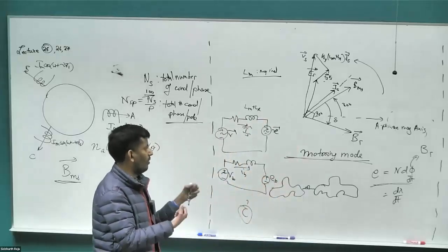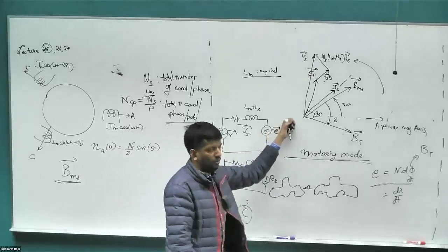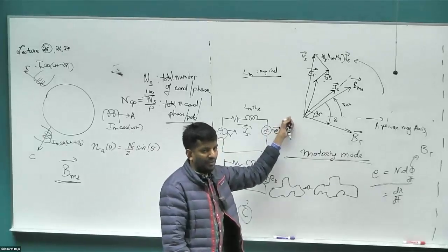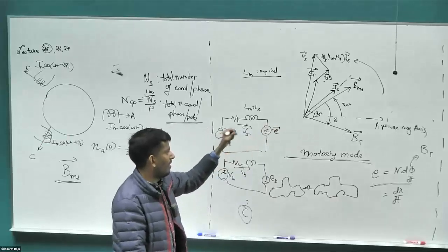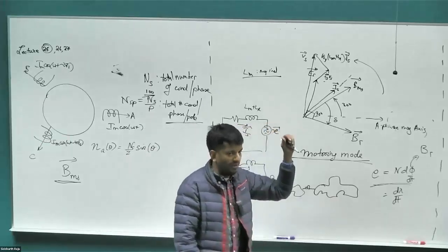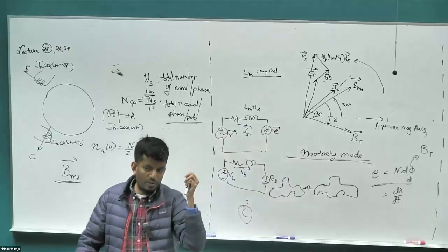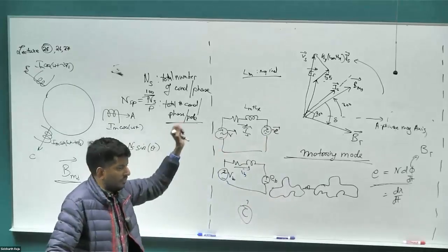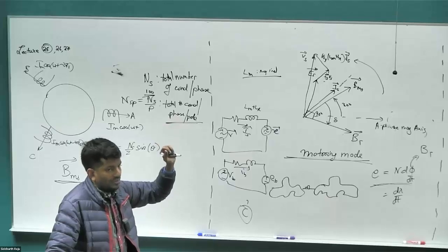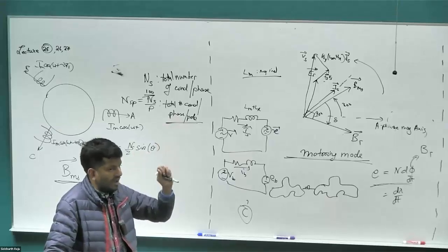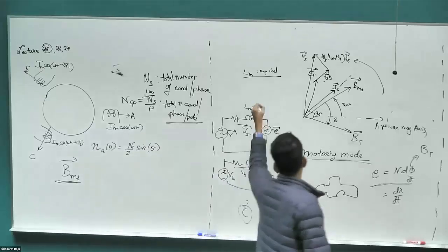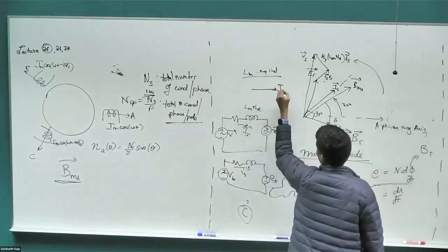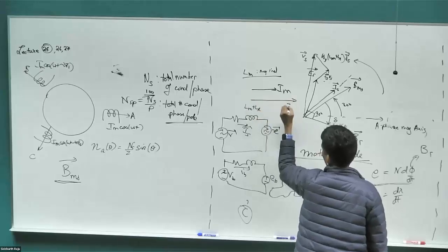All right. When you go to phasor, it's basically taking a screenshot of this space vector and drawing it for one particular time. That will give us the phasor value. In addition, you scale the value by a factor of 2 by 3. Because if the magnitude of your current is some 10 ampere, your space vector magnitude will be 3 by 2 times 10 ampere. But when you draw it as phasors, you will draw the magnitude of the current itself as a phasor value of just 10 ampere. Right? So when we draw our phasors, it would have just been Im. But when you draw space vectors, that would have been 3 by 2 times Im.